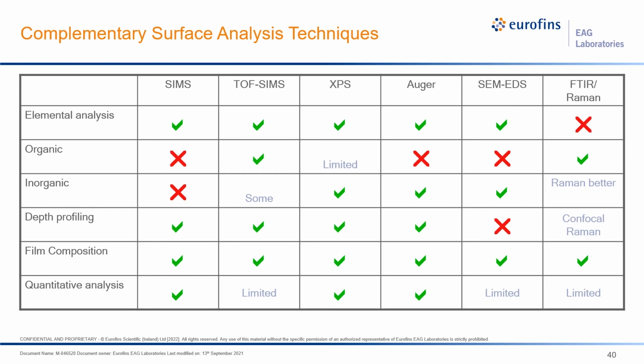Okay, so here's a little bit of a table summarizing the relationship of TOF-SIMS to some of the other adjacent techniques that I've mentioned a few times. So SIMS, not great at organic stuff, doesn't really get solid inorganic information. It gets elemental information that can be related to the inorganic stuff. TOF-SIMS, relatively strong across the board. Quantitation's limited. I didn't touch on that a whole lot in this talk, but with standards, we can measure some concentrations. XPS is pretty good there. It's limited in the specificity of the organic information it can obtain. And then I'm not going to spend a whole lot of time on these other ones, but they all are complementary in some way to TOF-SIMS, and you can often get data that is supported by two techniques rather than one, or supported by some imaging information at a higher resolution from something like SEM/EDS compared to TOF-SIMS.